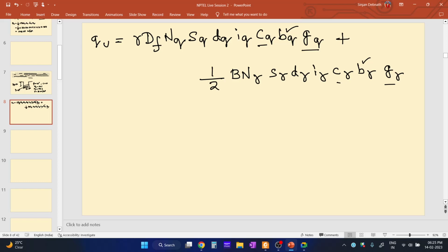Okay. So for strip footing, since this is a strip footing, sq is equal to s gamma is equal to 1, and the depth factor dq. So we need to find out, and also the load is acting vertical.